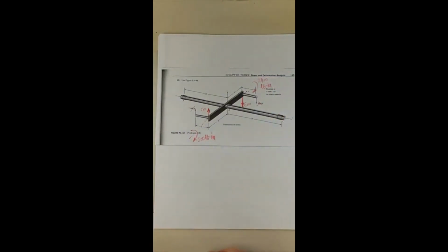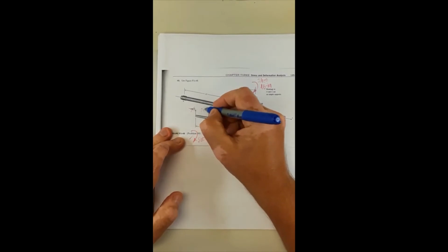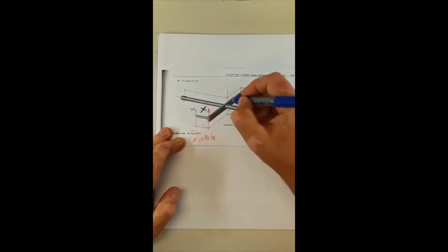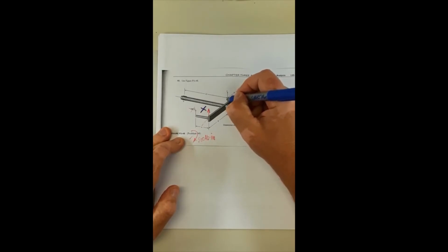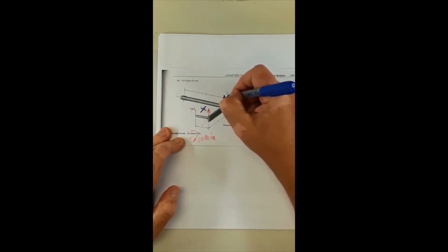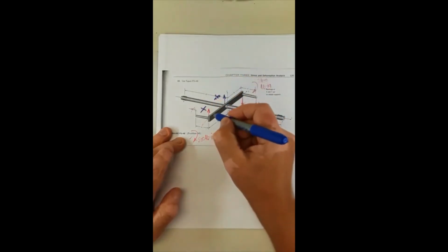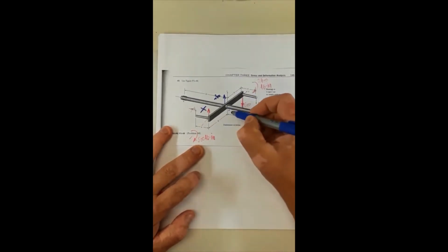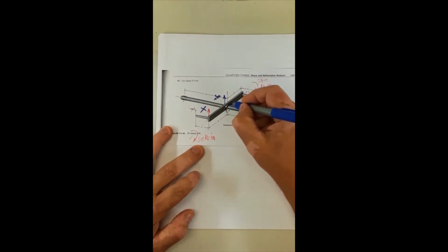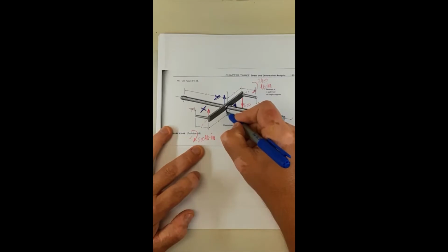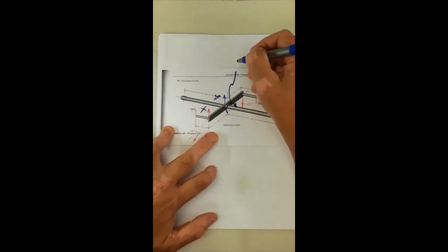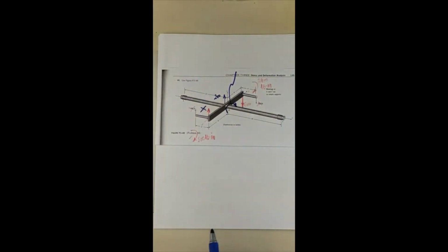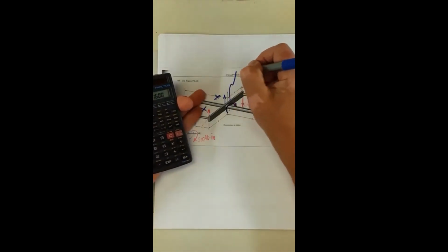Okay, so this was first move, and then if I take the force from here, the 200-pound force, and move it at B, so 200, then I need to account for this displacement along the x-axis by introducing a torque about the z-axis, and this torque is going to be equal to 200 times 8, which is 1600. So 1600.